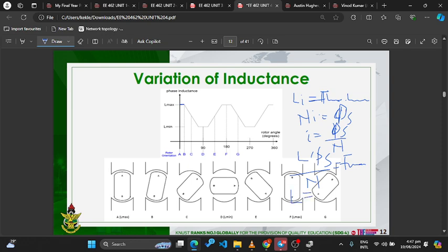Okay, so if I make L the subject, L should be equal to the flux linkage. I'll call it F. I'm not saying you use F to denote it, I'm just calling it F. F times N divided by phi S. So you can see the inductance and reluctance are inversely proportional. So remember, inductance and reluctance are inversely proportional. Oh, this reluctance is S. So they are inversely proportional.